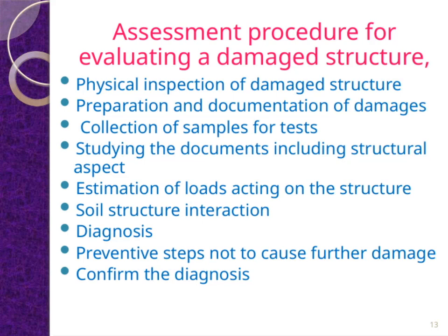Let's start with the physical inspection of the damaged structure. This step is crucial because it allows us to visually assess the extent of the damage firsthand. We carefully examine the structure, looking for cracks, deformations, or any signs of distress. Next, we move on to the preparation and documentation of damages. It's essential to record every detail accurately, as these records will guide our analysis and help track changes over time.